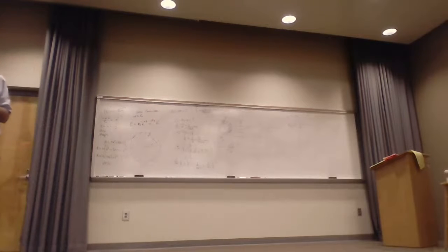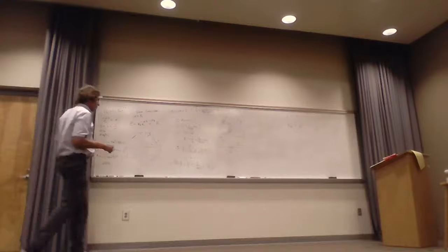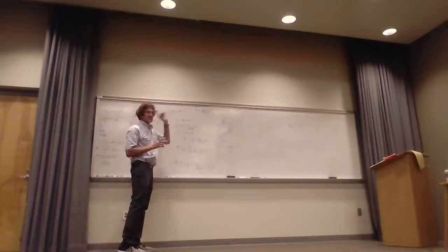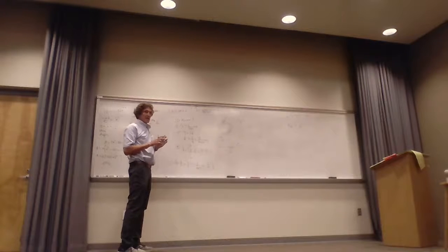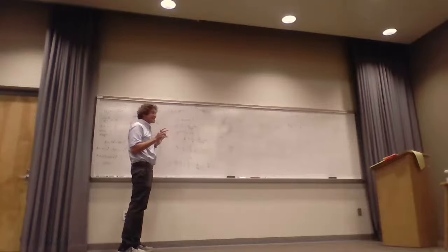If it seems like it's coming at you real fast, you'll catch up. You'll be using this stuff to do many, many problems. Skin depth will be second nature. It's like F equals ma in physics, or V equals IR. You'd use it so much, it just sticks in your brain. Remember, if skin depth is less than the radius, then you have to use that formula.